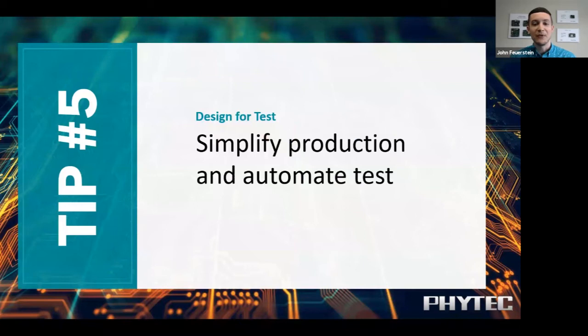All right, moving on to tip number 5. After layout's done, we want to go to production tests. But we want to make sure that we're thinking about tests during design as well. So simplify production and automate tests. It's very helpful to consider how you're going to test your system after and while you're designing it. And there are 2 kinds of design for tests: testing and verifying your design, and testing units as they are built in production. While additional circuitry increases costs and takes up space, the benefits can often outweigh these impacts. And so today we're just going to focus on designing for production tests specifically.